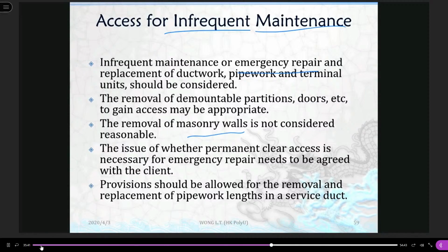Just to give an example, in Causeway Bay we have Times Square. At Times Square, the main plant rooms on the 12th and 14th floors hold the main chiller plant and even the transformer. The replacement life cycle for this equipment is around 15 to 20 years. Therefore, the maintenance work has to demolish the building facade.